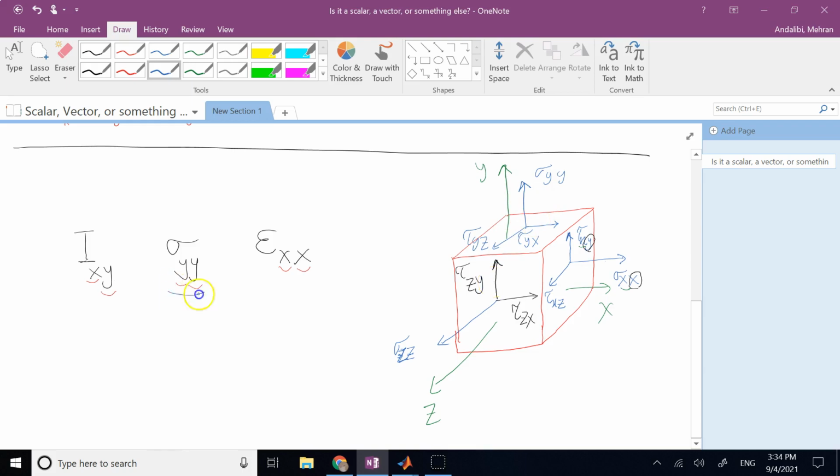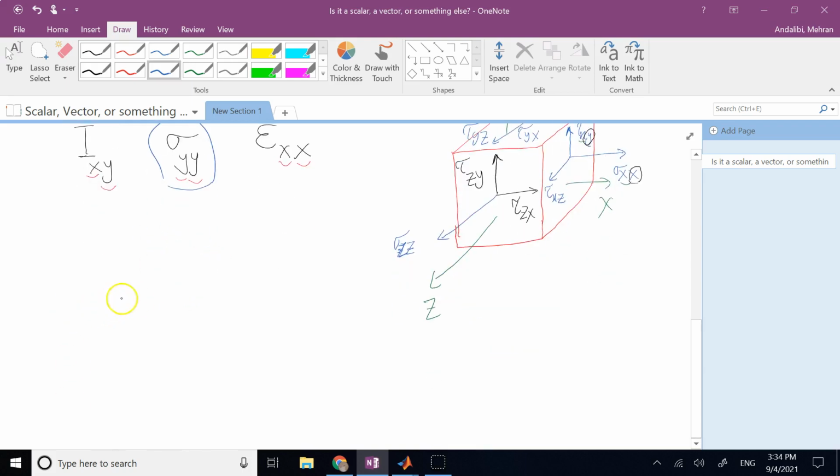So I say when you talk about the stress, right, it is really a matrix of numbers, correct? It is sigma_xx, sigma_yy, and sigma_zz. The normal stress is on the diagonal. And then off-diagonal elements are what? They are shear stresses like this, correct? Well, of course, in solid mechanics, you show that the matrix is symmetric and these elements are mirror images of each other.